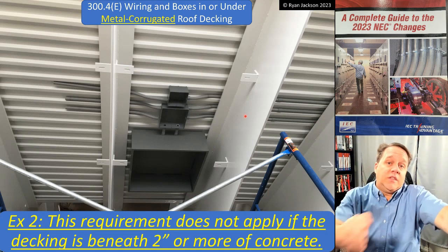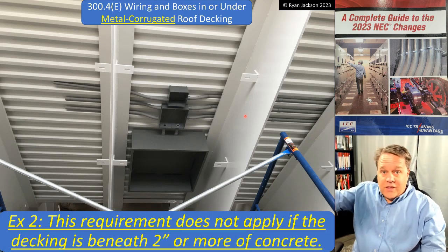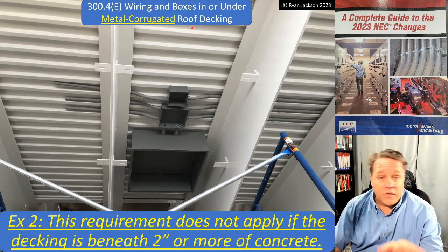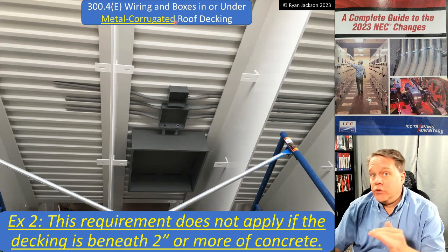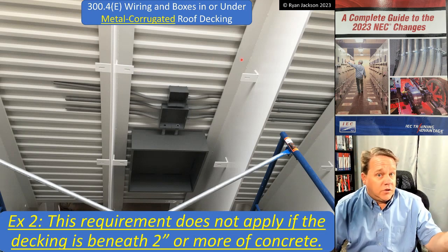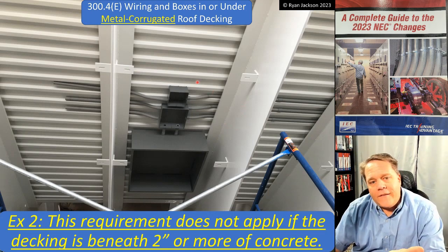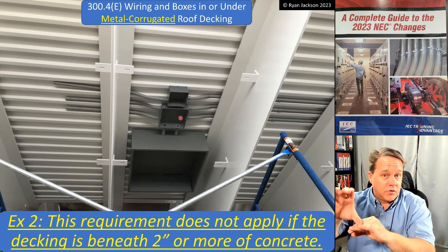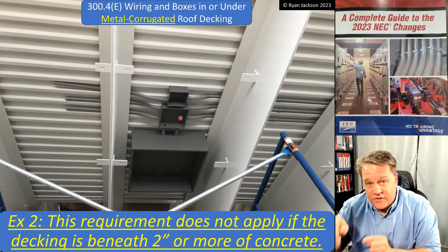You can take that off the roof and put it in your front yard and point at it and say, hey, that's still roof decking. So the fact that we say roof decking in the title doesn't necessarily clarify where this rule does and does not apply. The informational note clarified. It said, listen, we're trying to protect nails and screws from the deck, so why would I have to protect the cables and the raceways that are underneath 2 inches of concrete? Well, there's no reason to, and now the code specifically says you don't have to do it.